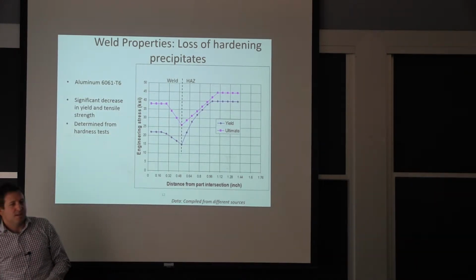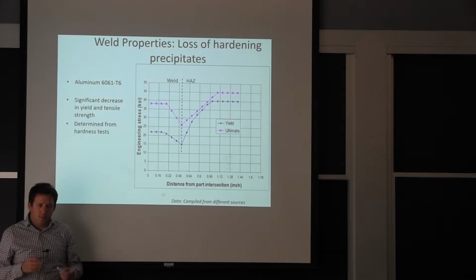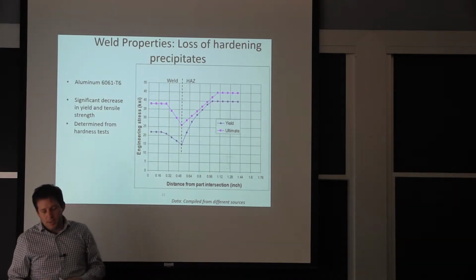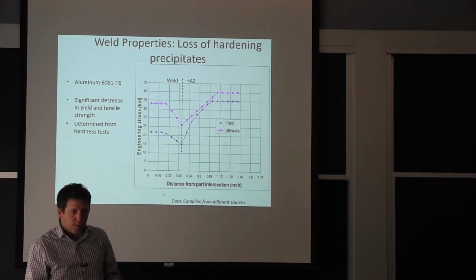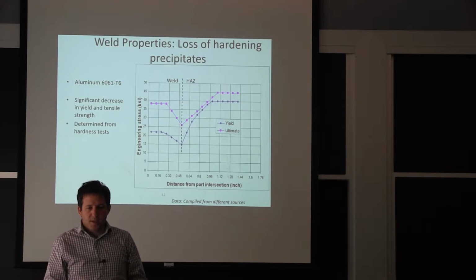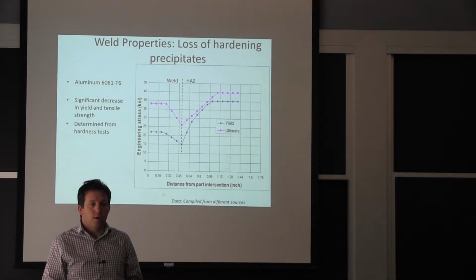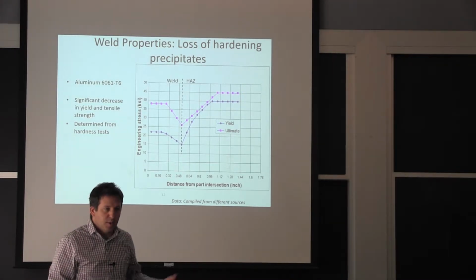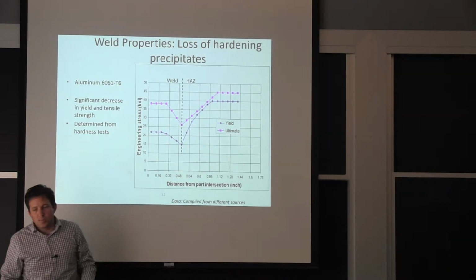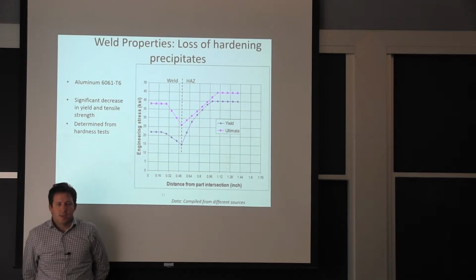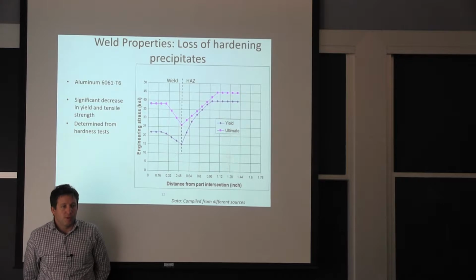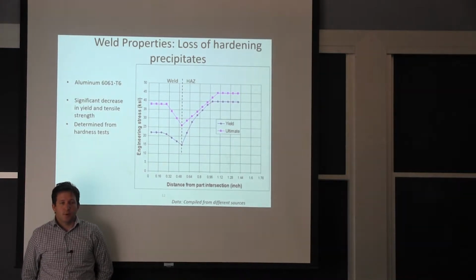I don't think it's done very much, but you're right. If you knew exactly the alloy, you could get into a certain temperature. One thing you will not be able to do is correct for the portion of the microstructure where, instead of re-quenching it, all you did is heat it and grow the particles. And that's a big part of what's going on here, because to put into solution, it takes time. It's not a question of reaching the temperature. You have to leave it there to remelt essentially those precipitate phase particles.